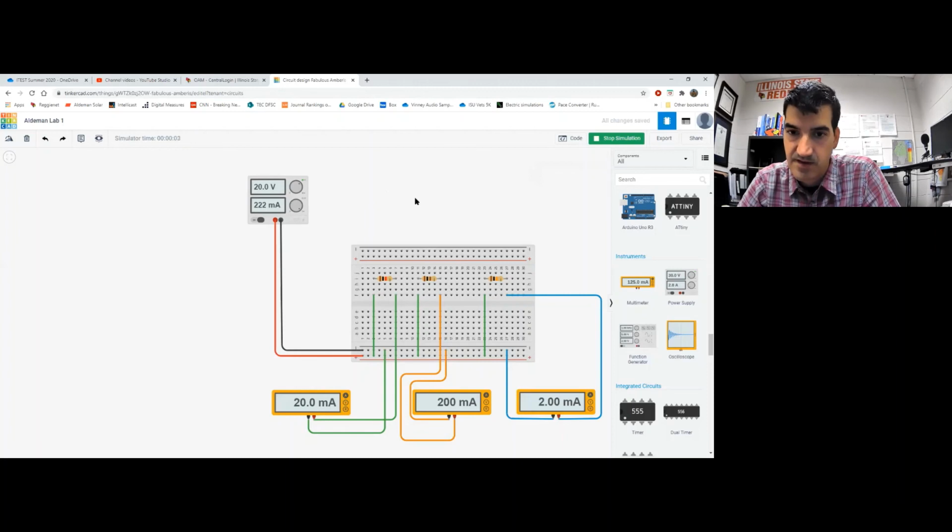There we go. All right, so you notice that they all have different current values. There's a different amount of current going through each branch of the parallel circuit, which makes sense because some branches have higher resistance than other branches. You would expect that the higher the resistance in a branch, the lower the amount of current. The lower the resistance in a branch, the higher the amount of current. So it looks like this one has the most current, this one has the least current going through it. So I can look at this and tell you that this one is the smallest of the resistors, and this one is the largest of the resistors.